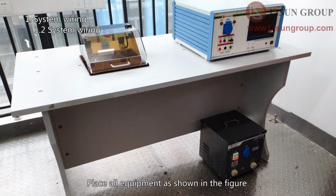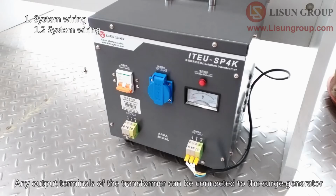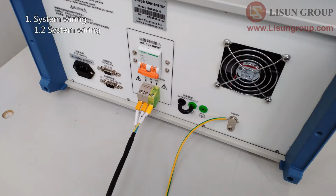Place all equipment as shown in the figure. Connect the ground line for the surge generator. Any output terminals of the transformer can be connected to the surge generator. Pay attention to the correct LNPE sequence. For safety, make sure the air switch is off.